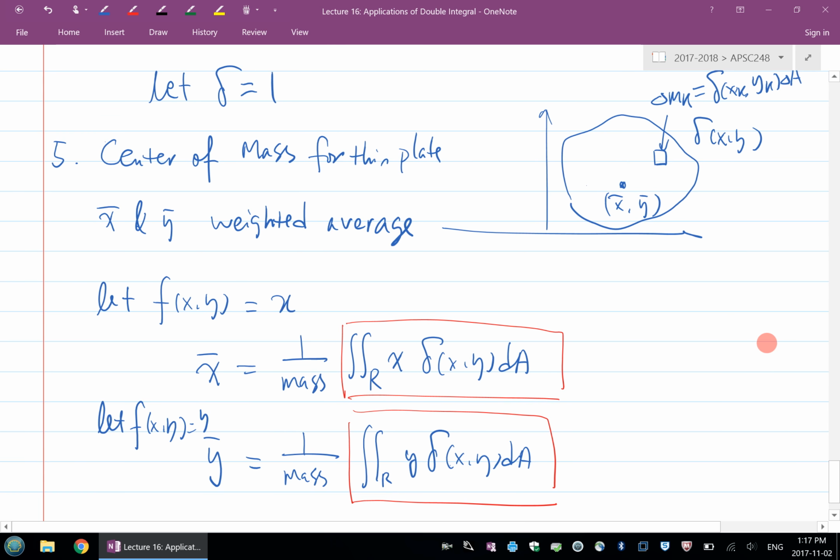Anyway, there's a concept called moment, isn't it? A moment equals the force times the distance, right? Now I'm going to extend the moment concept. I'm going to create another concept called mass moment, not the force moment. So what is a mass moment? You use a small mass times the distance, and then you get a concept called mass moment.